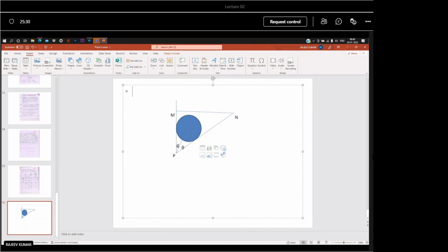First you draw the free body diagram. Weight is acting in the vertical direction, so calculate the summation of all the forces in the vertical direction equal to 0. Then draw a perpendicular to PN from the center of gravity G of the log till point J. Calculate the length PJ.